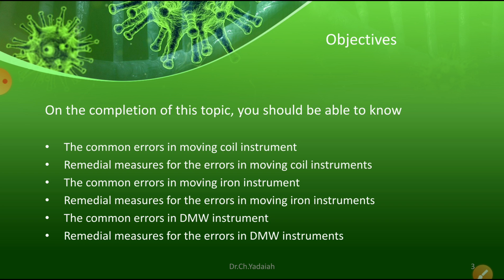And also stray field. Because all are electromagnetic fields, these fields are very weak in our instruments. If these instruments are near a strong magnetic field in the surrounding area, that magnetic field affects our instruments, which leads to errors while reading.